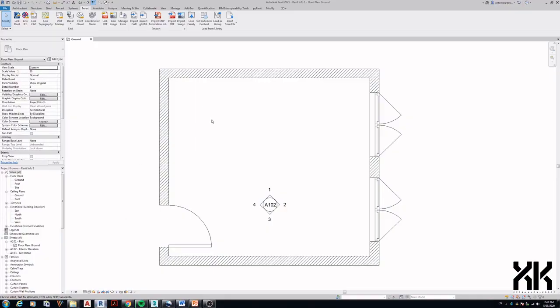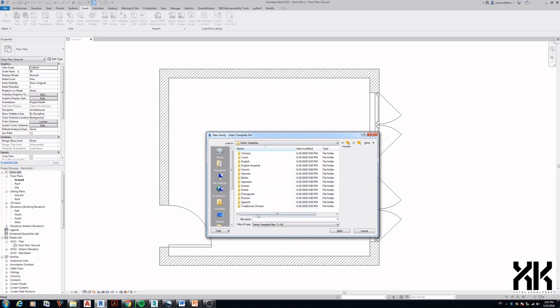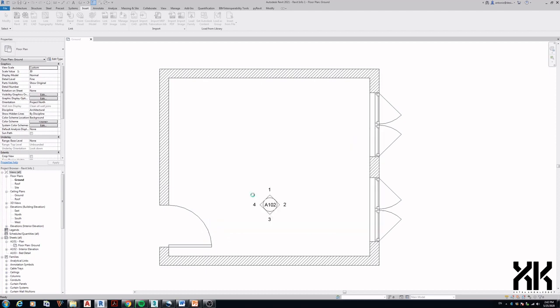In Revit, let's assign our models in detail level. This time, instead of inserting our DXF file directly in the drawing area, we will create a furniture family since our model is side tables and lampshades. Click File, Family, select English folder, and select Metric Furniture Family Template.